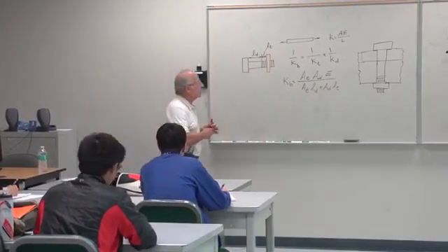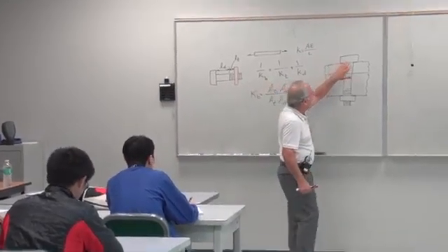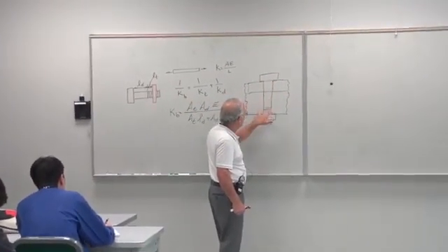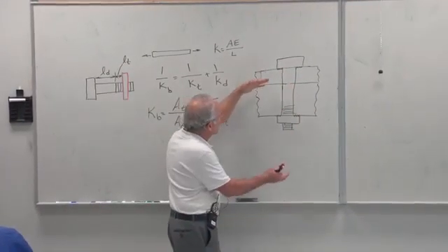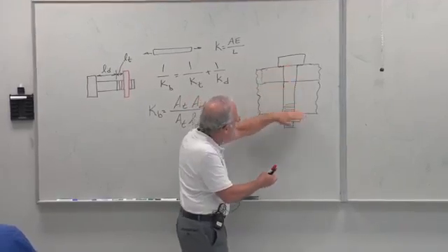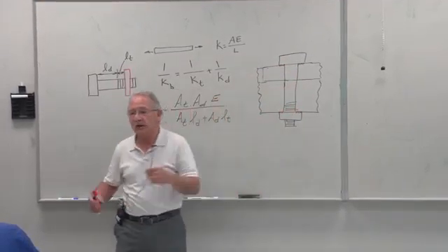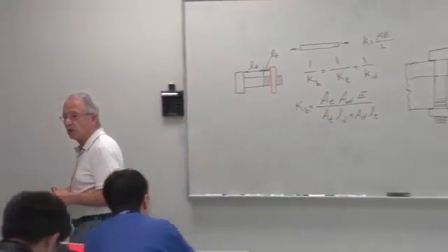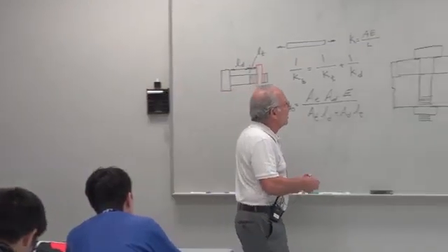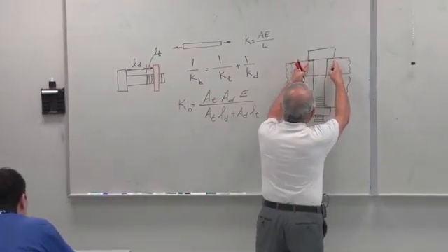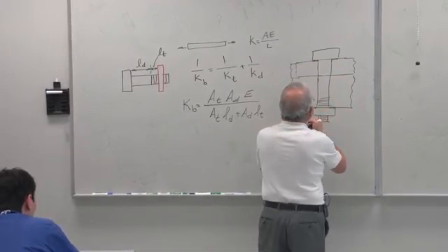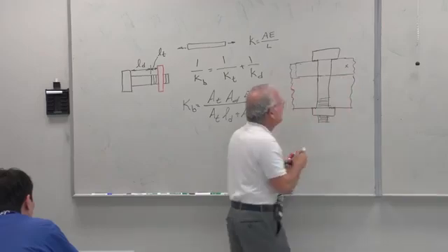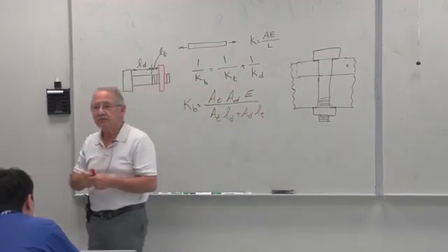Now, this load from the underside of the bolt needs to be transferred to the top of the nut or vice versa. In other words, this grip that you have creates a force throughout this member. That's how we affect the joint. That's how the members are kept together. So the question here is, does this load travel through these two members straight down like that? In other words, if I take a look at this point here, I see no compression. Is that right?